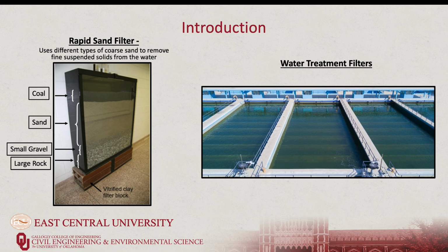And so in water treatment systems, they will have large basins filled with different size media, similar to the column shown here to our left. Using a rapid sand filter on a large scale can help remove suspended solids in larger quantities of water so that the receiving cities and towns have clean drinking water. Many of you who are on city water or receive water through a distribution system have been using water that has been treated through sand filters. Sand filters have been found to be the most cost-effective way of treating large amounts of water for communities to use.